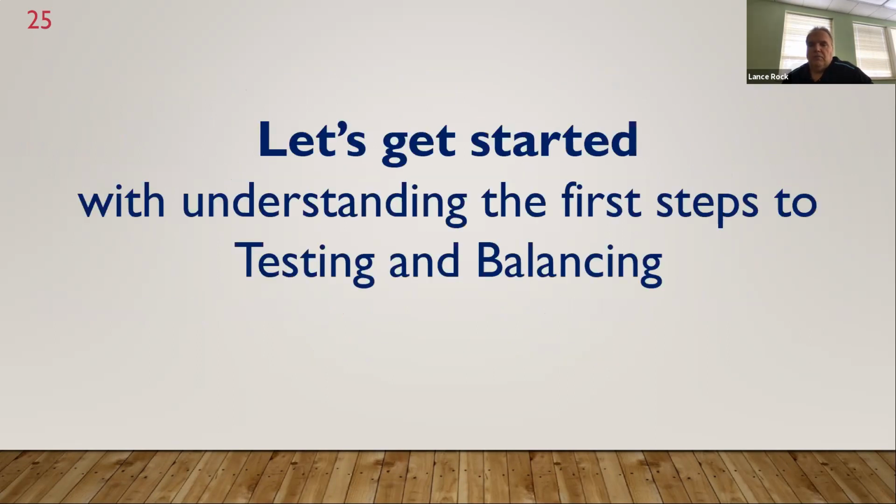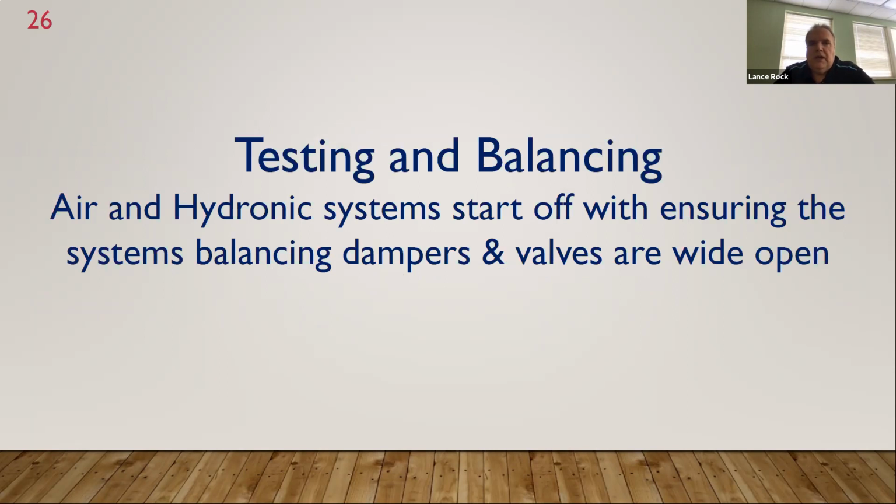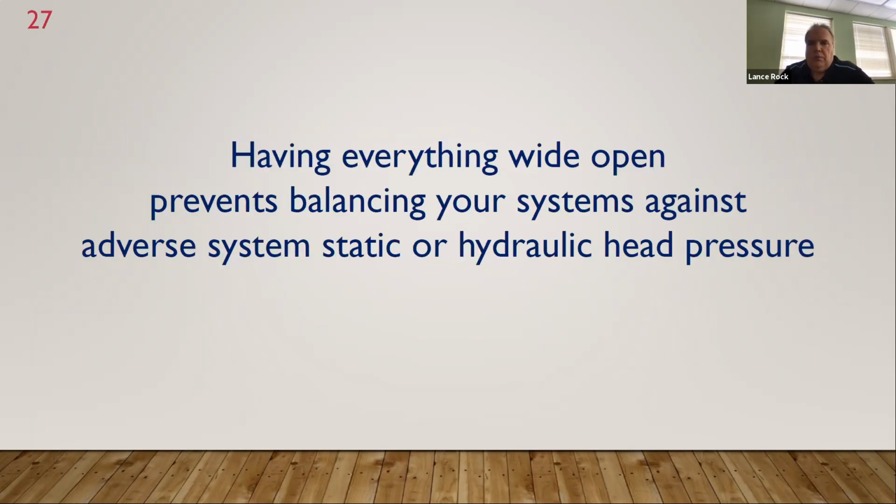Next, please. Let's get started understanding the first steps of testing and balancing, where we can start saving money. Next, please. Testing and balancing air and hydronic systems start off with ensuring systems, balancing dampers, and valves are wide open. Go through the system, read it out, and make sure everything is wide open.